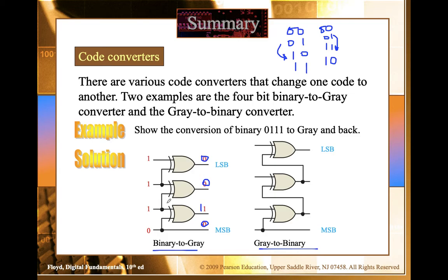Okay, so now this code is the 3-bit. I showed you 2-bit gray code earlier, and now this is a 3-bit gray code. Now a 3-bit binary is being converted into a 3-bit gray code. So it's a very simple encoder that is being designed to show how to convert from binary to gray. Just remember this thing, okay?